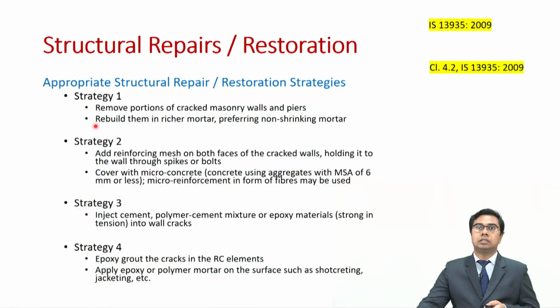There are multiple strategies for that. Let us look into some common strategies. These are obtained from clause 4.2 of IS 13935:2009. I suggest that you keep a code copy with you, so that you can have a look while you go through these video lectures. So, the first strategy is to remove the portions of the cracked masonry walls.